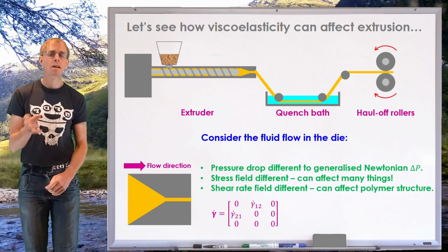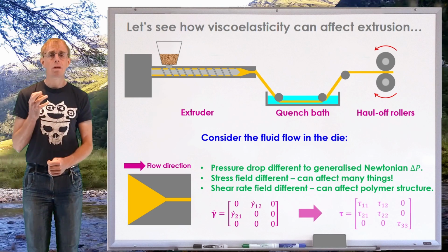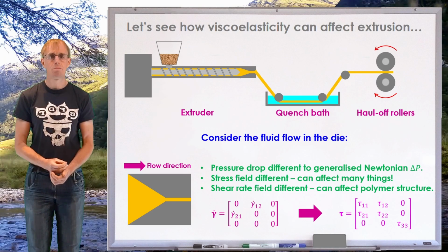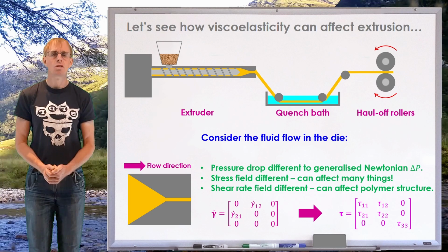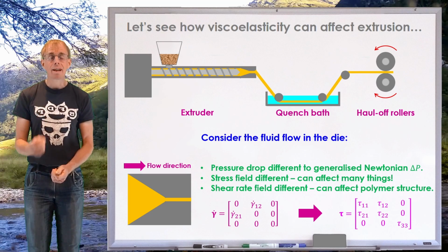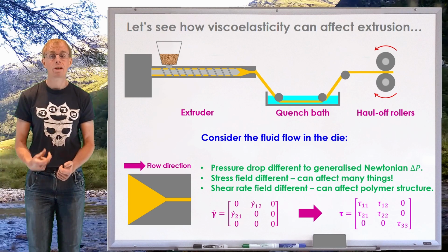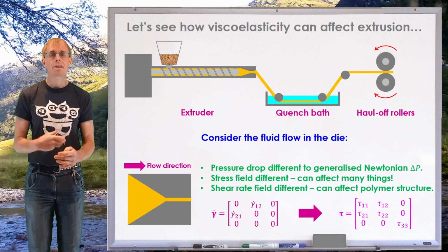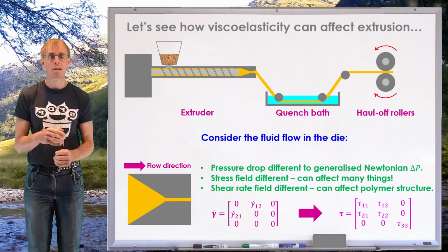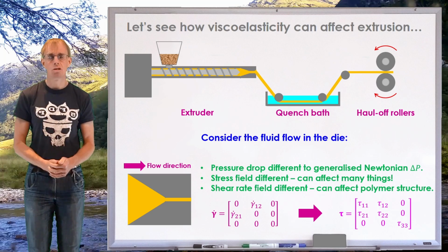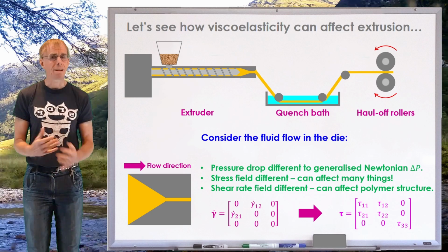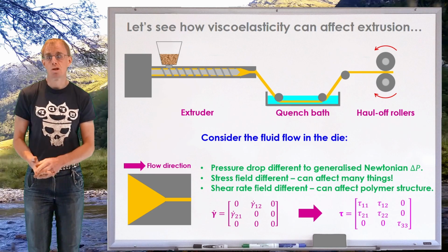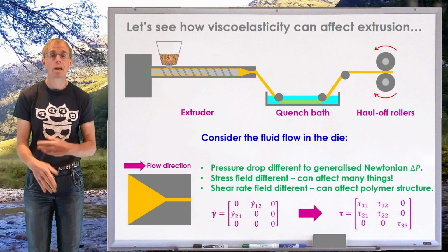If, however, we look at the related stress tensor for a viscoelastic material, we cannot ignore the presence of normal stresses. The constitutive equations that we'll explore in the next lesson will again really highlight this. For a given simple shear rate field, such as that gamma dot tensor there, they will have entries in the stress tensor in the normal directions. And so this is fundamentally why things are different. For polymeric fluid, normal stresses are generated by simple shear flows. So you're going to get more effects.